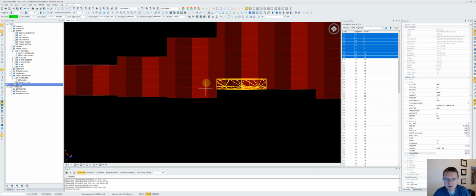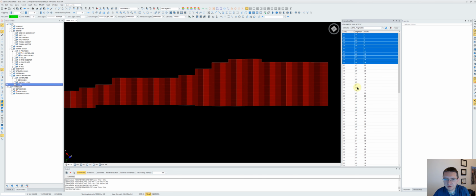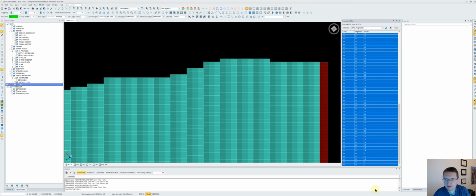It works fine. But you may want to make sure all of your center lines are starting and ending at the same spot. And the other thing is, the burden, we did 3 meters, and so you probably want the length of the center lines in an increment of 3 meters. That way it creates the same number uniform. But this is close enough, I think, for what we need.